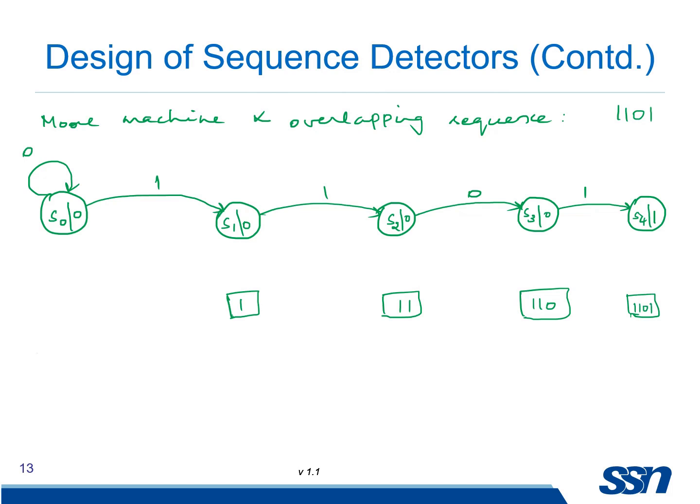So now here we shall start. If I receive a 1 after coming to the state S1, it is going through the sequence, so it moves to the next state. If it is a 0, we compare. This is not equal, so I move to the previous state. Then here, if it is a 0, it moves to S3. If you receive a 1, you compare the last 2 bits with this 2 bit. If it is same, we remain in the same state. If it is not same, we check the last bit with the 1 bit value. That's how the procedure is. So this is 1.